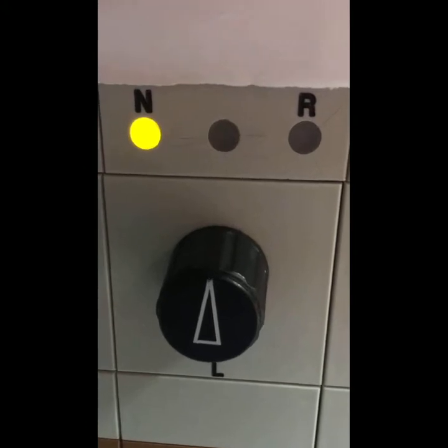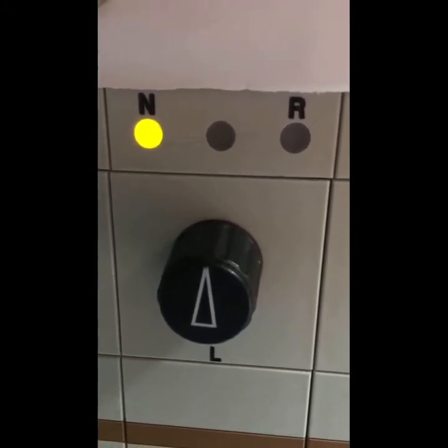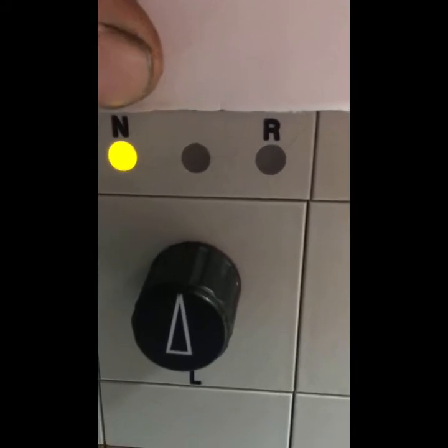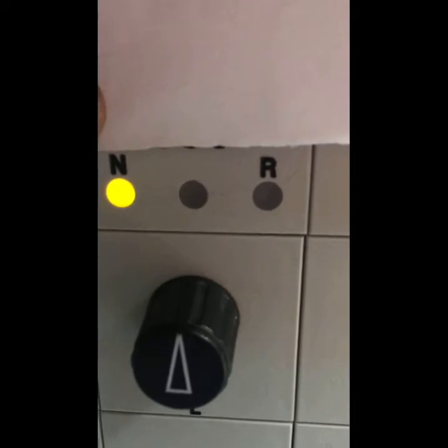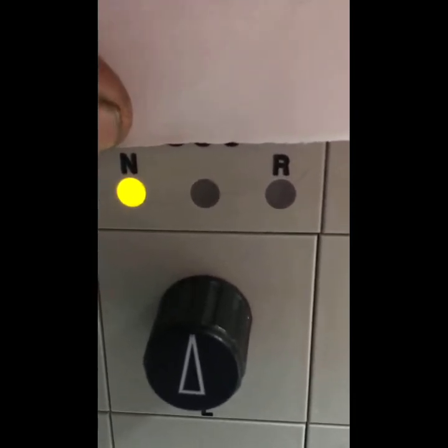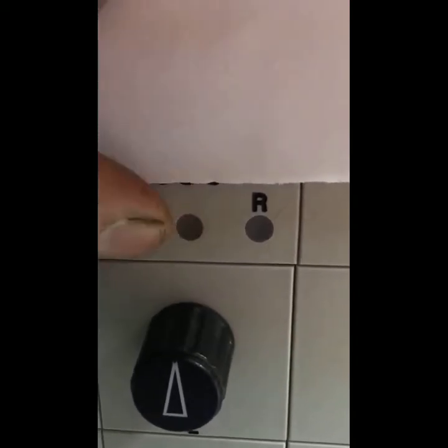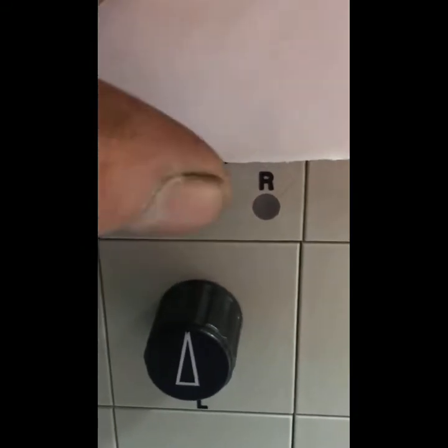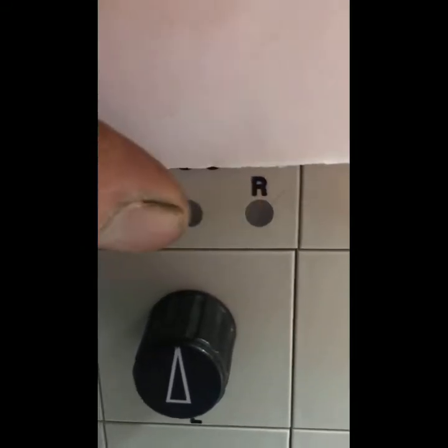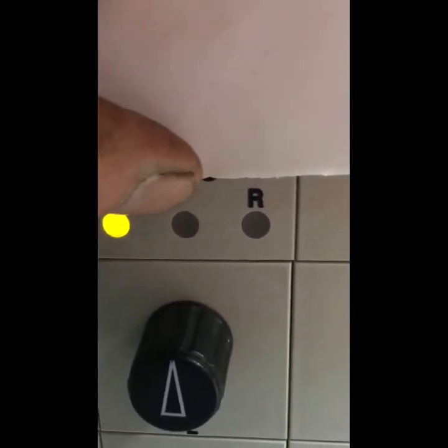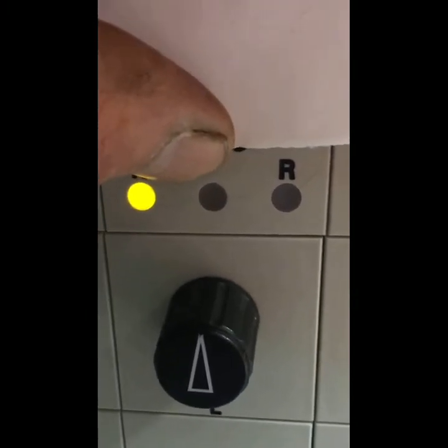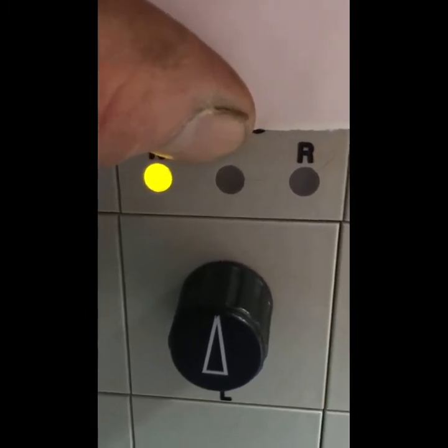And here, as previously mentioned, is our point key. So as you can see, it sits normally in the centre, and the centre light will be non-illuminated. When we command it normal, it goes to the normal position. These points last were in the normal, and when the route is set, the indication will go out, go over, the opposite indication will move to suit whichever route is selected. And when we're done and we want to put everything back onto the panel, we'll set it back into the centre position again. This is the flashing out of correspondence light in the centre if we don't get our detection within the allotted time, 7.5 seconds.